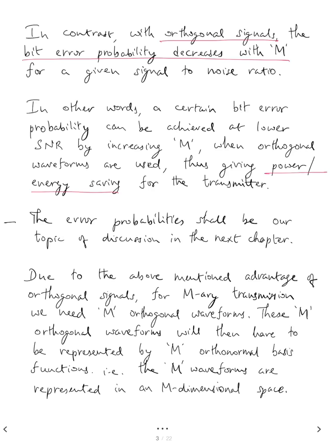If you want all the signals to be orthogonal to each other, that means we need to have each signal on an axis, and only one signal should be on a particular axis, that is on a particular basis function. So if we have, say, 2 dimensions, then we have 2 signals. Each of the signals lies on an axis, on the x-axis and y-axis, for example.